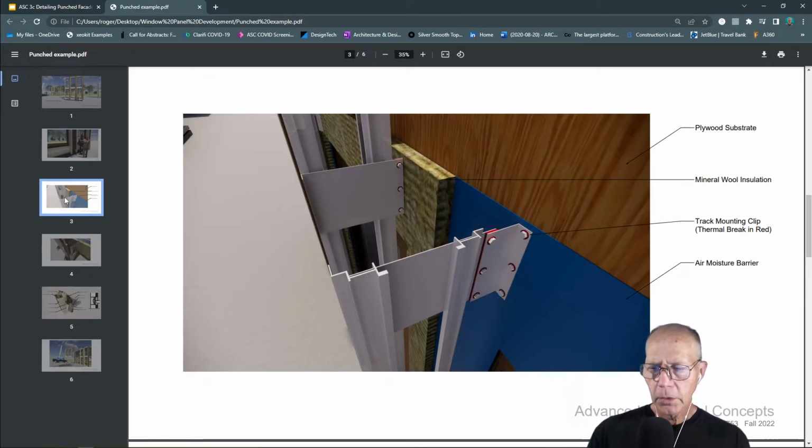And I want to point out the idea of thermal breaks. So you can see this metal structure sticking out into the cold facade or the hot facade, and then that metal transferring that heat back to the building plane, the envelope of the building. And as we've discussed in lecture, the idea is that we want to make sure that we eliminate as much thermal transfer there.